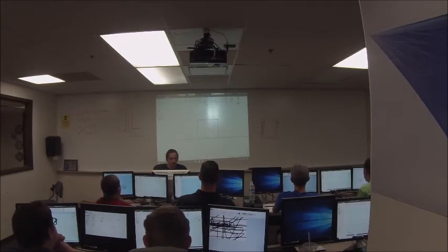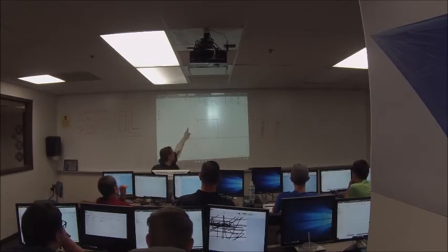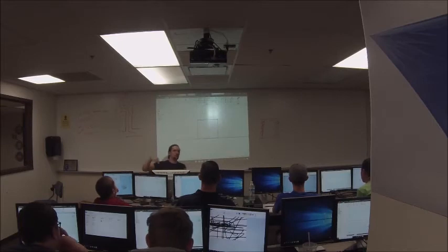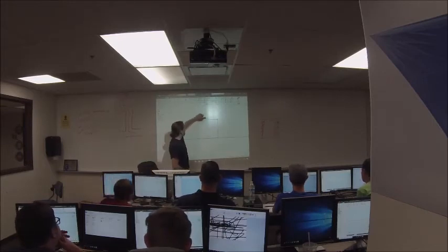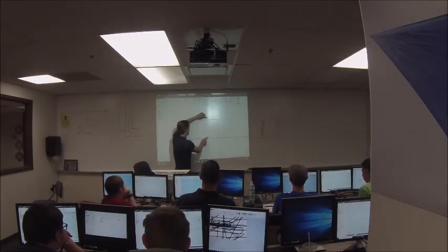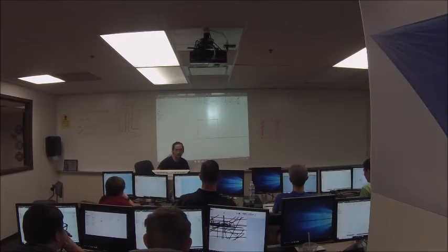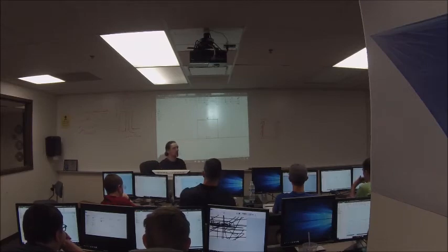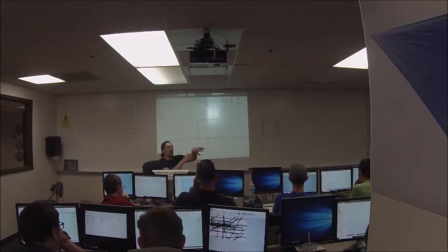So what I do is I hover over these yellow squares at the corners, and you'll see a couple icons appear. There's going to be an icon for each piece of geometry that's involved in a constraint. For instance, this symbol and this symbol here, these two parallel constraints, these two lines that are parallel, these are both the same constraint. If I hover over one line, you can see both lines highlight, and both constraints highlight. So if I delete one of these, I delete the other one. The icons show up in pairs.